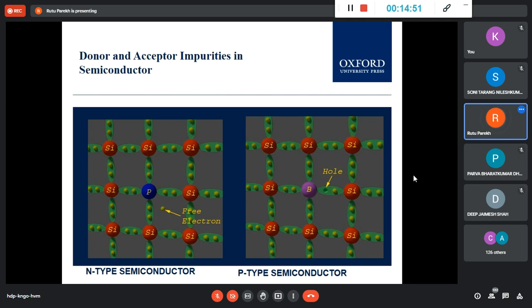We make an application. So here N type is, so we now need more conductivity in a semiconductor than what it can offer, right? As I said, we want more current, how will we get it, with more conductivity. Current can be because of the hole, because of the electron. Here in the diode, you have flow of both electron and hole. Okay, and they both are moving, and we'll see how, and then it is creating a current. Now you have N type. N type is a pentavalent impurity, for example, phosphorus. When added in some amount, you will get this kind of lattice structure.